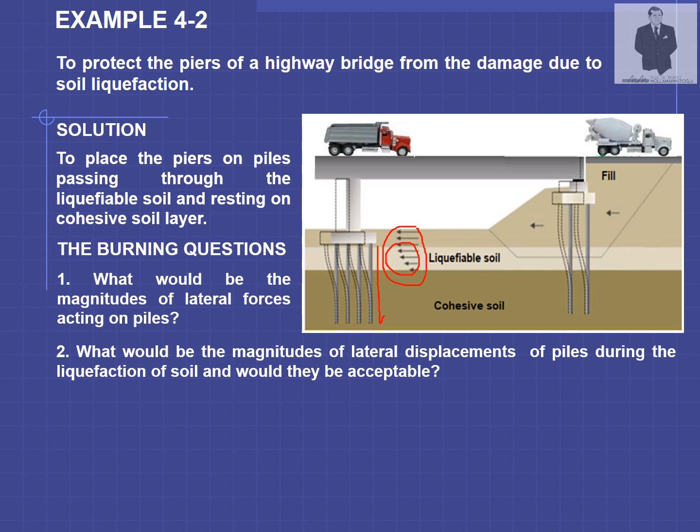Now, you see the displacement of the piles. When the soil liquefies, there will be increased lateral forces on piles. And we should secure that the lateral displacements of piles are limited. Otherwise, the bridge deck slab, as shown here, may collapse.